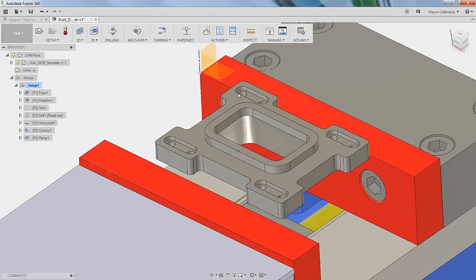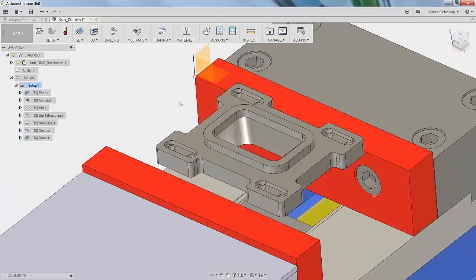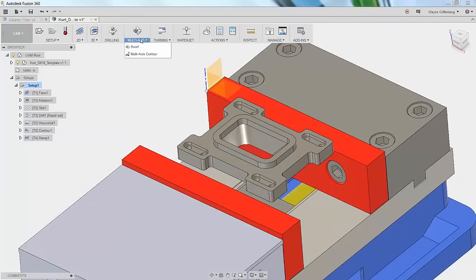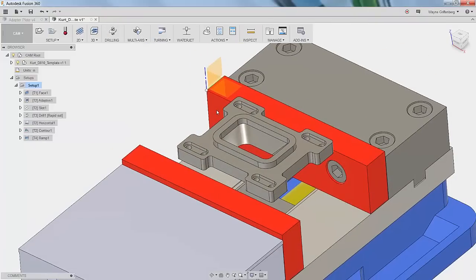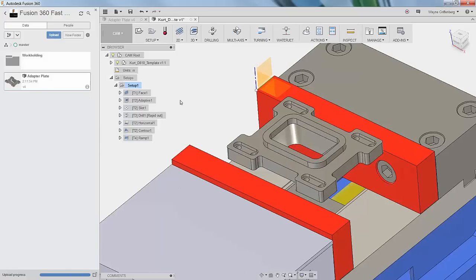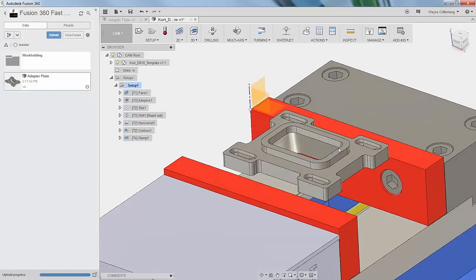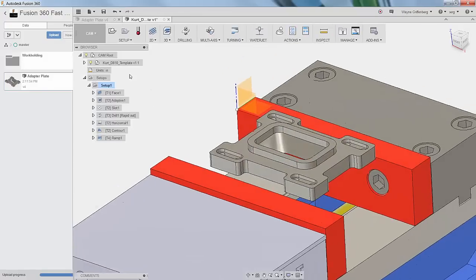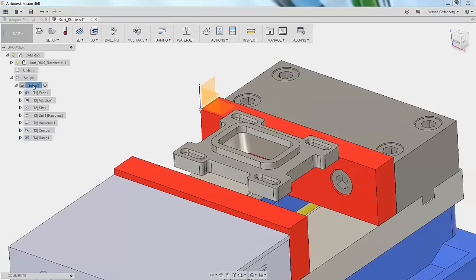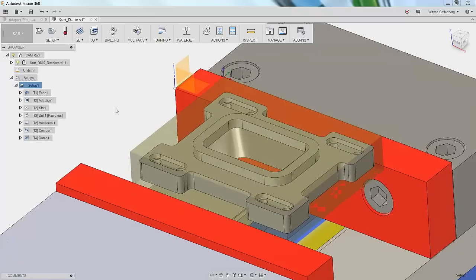We're able to apply some joints to be able to assemble these things and make it a sliding jaw or moving jaw. We're able to bring a part in from our data panel, that part we created, set it up for going into CAM to get some toolpaths on it. We're able to do a setup on the part using the solid model we created as our stock, able to get some toolpaths on there really quickly to rough it out.